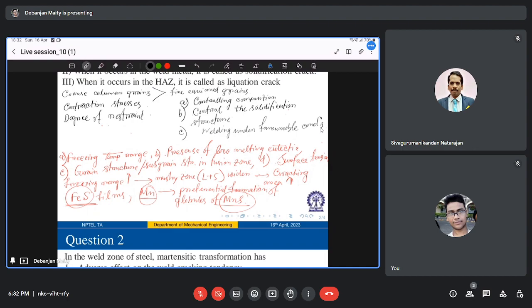Now the filler metal composition, the flux or shielding gas, process operating parameters, and welding procedures, including prevention of dilution, must all be carefully considered and selected to control the weld metal composition and minimize solidification cracking. Let us understand with some examples. Copper in aluminum alloys can be used to control the freezing range and the amount of eutectic liquid. You can also control residual element contents such as sulfur and phosphorus in steels or nickel based alloys. Then there can be manganese content in steels to control the distribution of low melting segregates, as I was mentioning, such as iron sulfide.